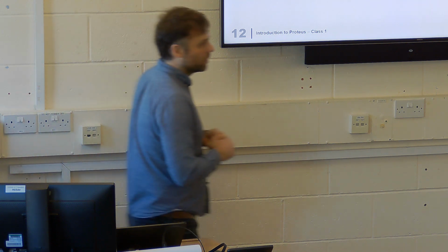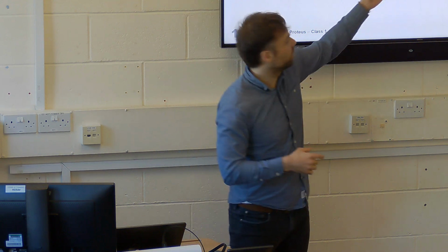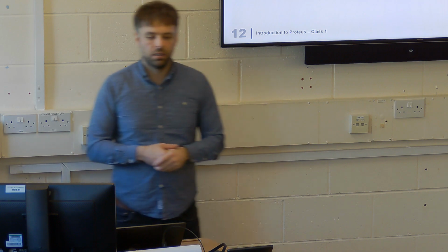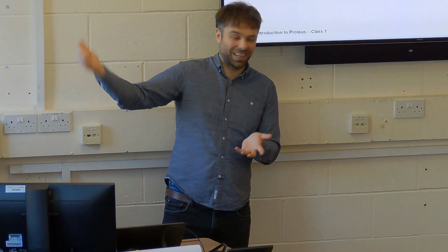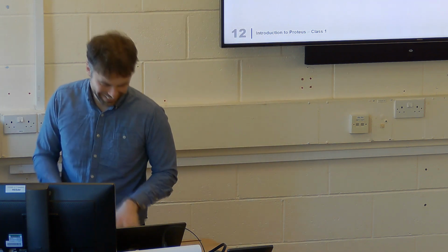And what happened was the graphics chip in the Xbox was getting hot and cold and hot and cold and hot and cold. It made the solder brittle underneath one of these BGA packages of the graphics chip package. One or two of the solder joints disconnected. The thing just wouldn't boot. So I used to buy them off eBay, put them in the garage, get one of these heat things, and resolder them and sell them on again.